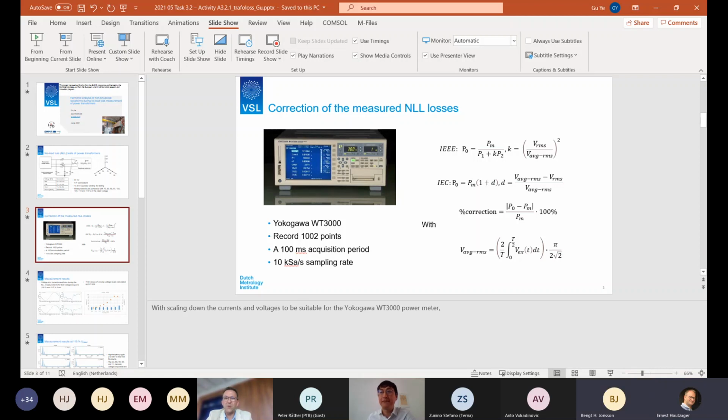How did you measure or establish the harmonic losses? We recorded the waveform, both of the voltage and current, and we did a Fourier post-processing, a Fourier transform, and we get the components. Then we calculate for the different frequencies, or different orders, individually with the phase angle. So it's post-processing of recorded waveforms.